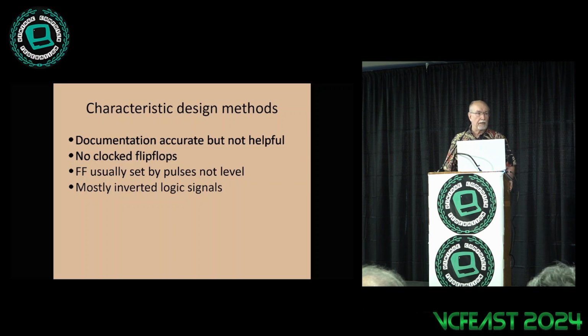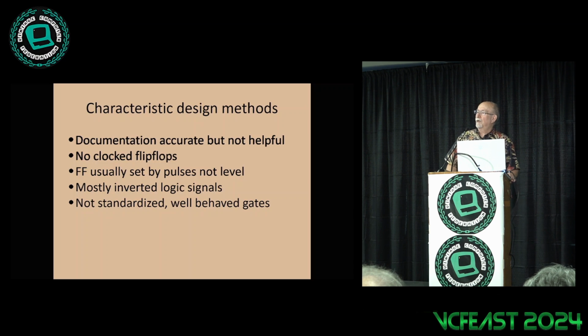IBM loves inverted logic. So you'll find most signals are something like minus stop. And so if minus stop is true, then it's running, because it's not stopped. So you have to get your head around that as you look through all of these things, combining signals that are not minus stop and minus sector mark and so on. Their gates are not nice, standardized, well-behaved gates like we have the privilege of dealing with in more modern technology. And I'll give you a couple of really interesting examples as we go a little further through here.